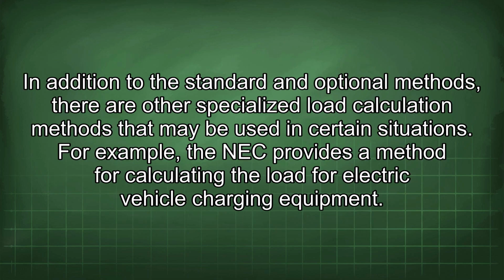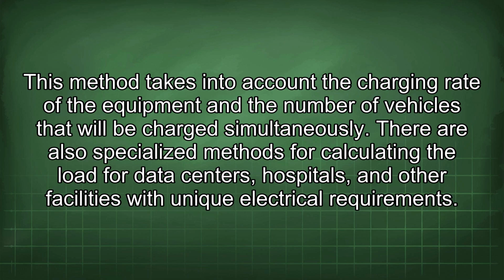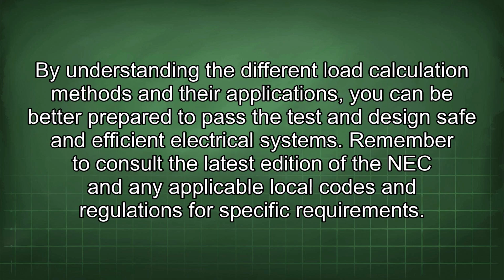In addition to the standard and optional methods, there are other specialized load calculation methods that may be used in certain situations. For example, the NEC provides a method for calculating the load for electric vehicle charging equipment. This method takes into account the charging rate of the equipment and the number of vehicles that will be charged simultaneously. There are also specialized methods for calculating the load for data centers, hospitals, and other facilities with unique electrical requirements. By understanding the different load calculation methods and their applications, you can be better prepared to pass the test and design safe and efficient electrical systems.